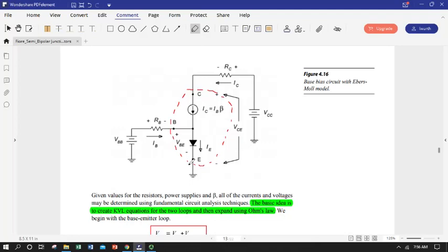Between point C and point E, we can measure a voltage difference, VCE, the voltage drop. So we have our constant current source. We know how much current it's going to give us, depends on the beta, and we're going to establish the IB depending on what voltage source is here and how big our resistor is. We know we're going to have a 0.7 volt drop going from B to E because we've got presumably a silicon based transistor, so this is going to have 0.7 volt forward bias. V forward takes its toll in voltage like any diode would, and away we go. Now we can apply Kirchhoff's voltage law to the base emitter, and then once we've figured that out, we can go on and use Kirchhoff's voltage law, collector to emitter, and usually solve for this.